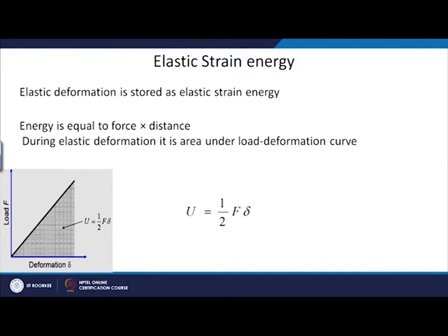So, if instead of plotting stress versus strain, I plot deformation versus load, the area under the curve will be equal to half of force into displacement, and that will give me the area under the curve. So, this is my elastic strain energy which is stored in the material when I am deforming it, and when I release the force, this strain energy will be recovered.